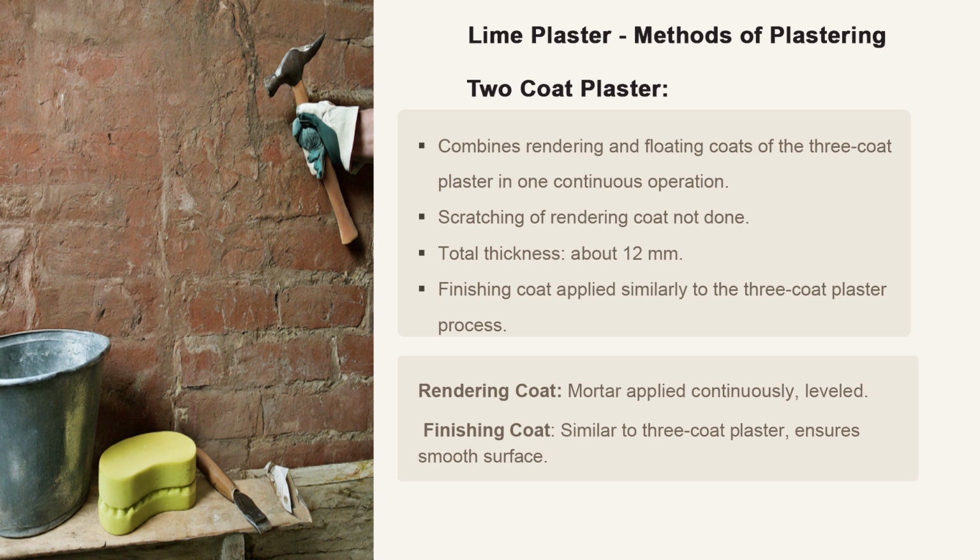Okay, let's move to cement plaster and cement-lime plaster, where we will learn how these materials are applied in different coats for various types of surfaces. Cement plaster can be applied in either 2 coats or 3 coats, with the latter being less common. So, 2-coat plaster. Again, we prepare the background by raking joints about 20 mm deep, cleaning the surface thoroughly and ensuring it's well watered.